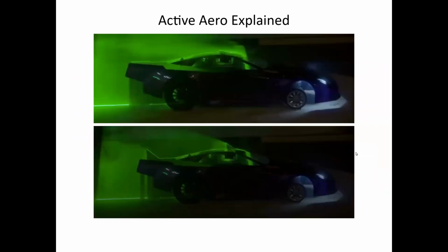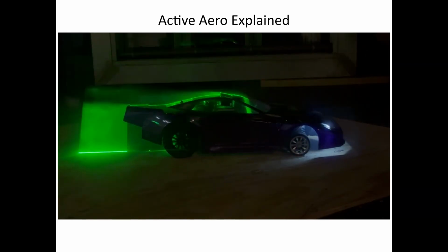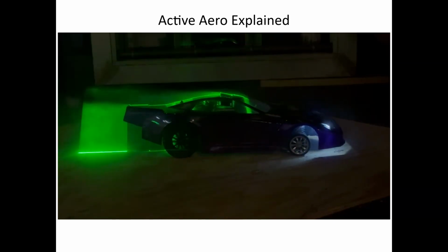So just like the previous picture, we did this with ours. These pictures are located in the wind tunnel that we utilized to test. The top picture is the drag reduction system on. Our wing is closed, meaning that it is not providing any extra downforce. And you can see the wind glides very smoothly and efficiently over the vehicle. And you can't see any movement along the wind or downforce or low pressure zones.